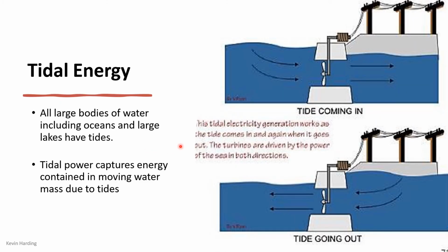The next one we're going to look at is tidal energy. So tidal energy is going to be different to hydropower in the sense that tidal energy is going to be 100% from the sea. The idea of this first option is that we have a large body of water and we get a large flow. So when the tides are coming in, the water is high on the outside, we have high tide on the left-hand side here, and that water rushes in through, and again, it's a straight kinetic energy conversion. There's the turbine again. The water rushes through, turns the turbine, and we have electricity.